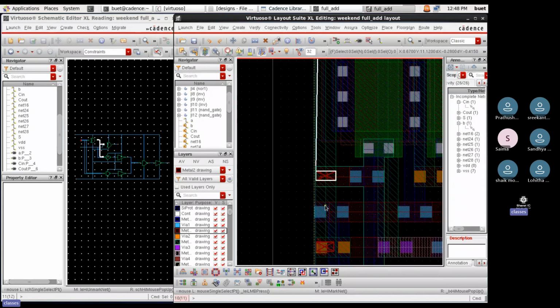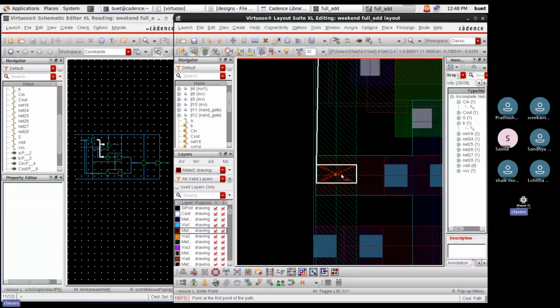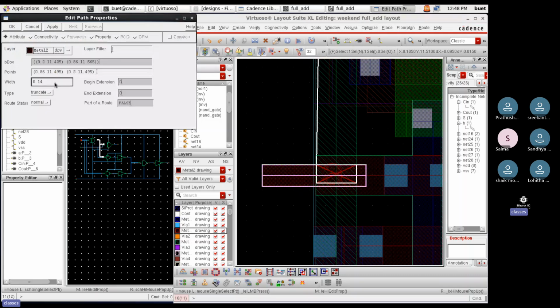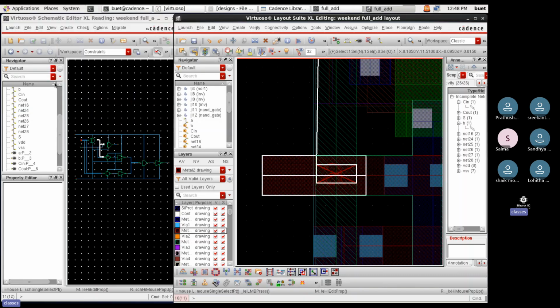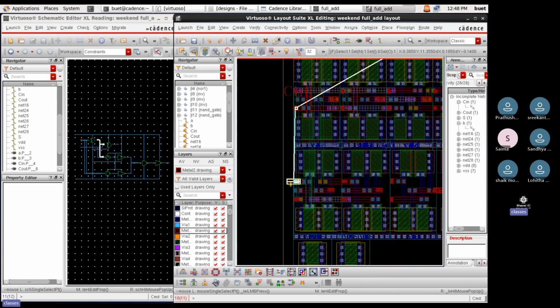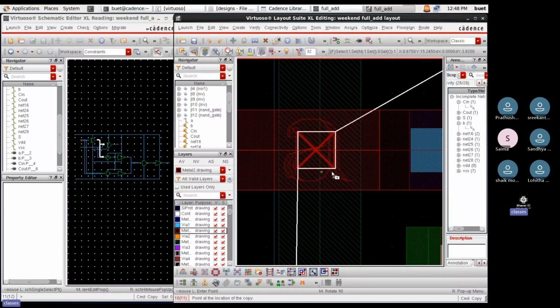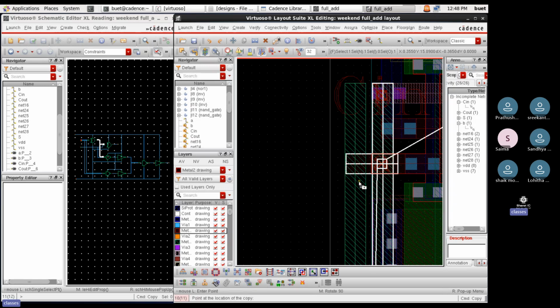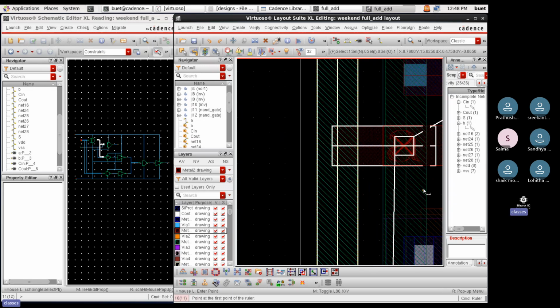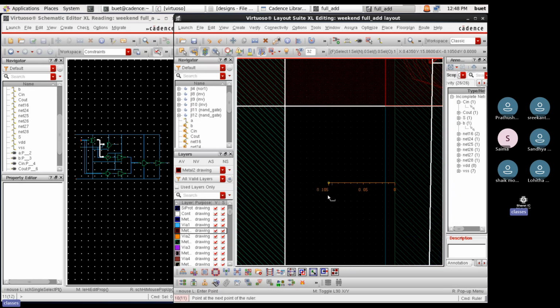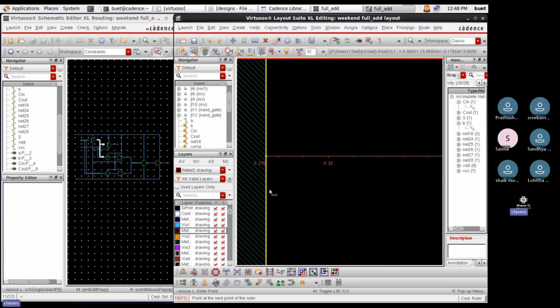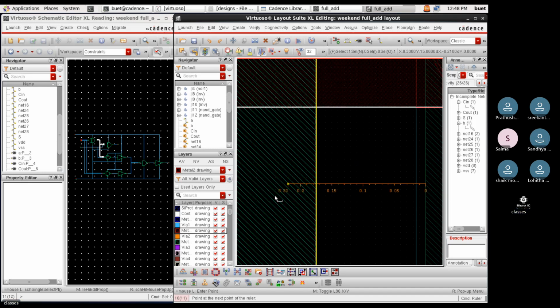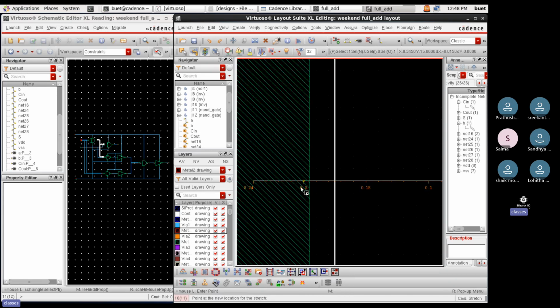For this one, what I will do is simply pull the metal 3 a little bit outside and make it 0.26 here. Okay. And the same metal 3 I will copy and paste here also. Then I will take this M3 outside by maintaining a distance of 0.2 micrometer minimum. Okay, 0.2 micrometer minimum I need. This is the DRC distance between the parallel lines.